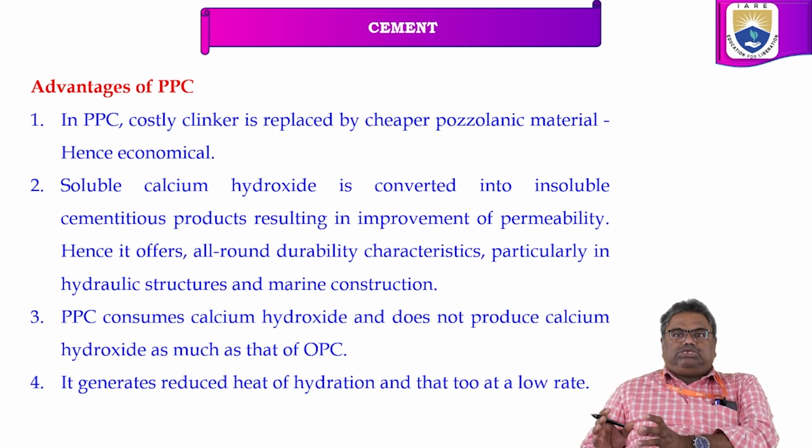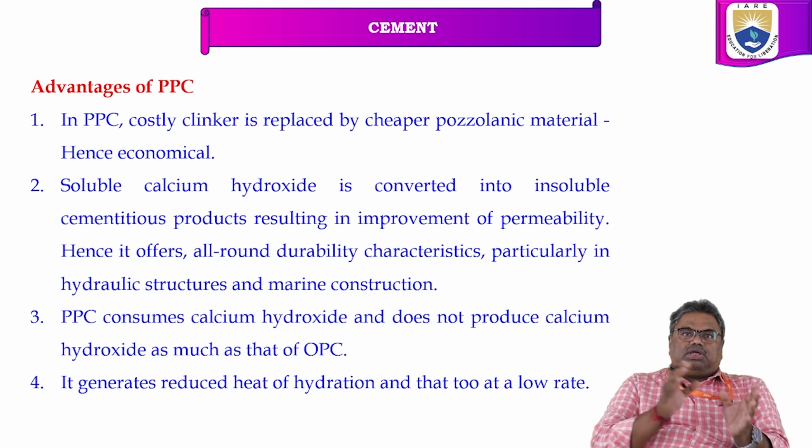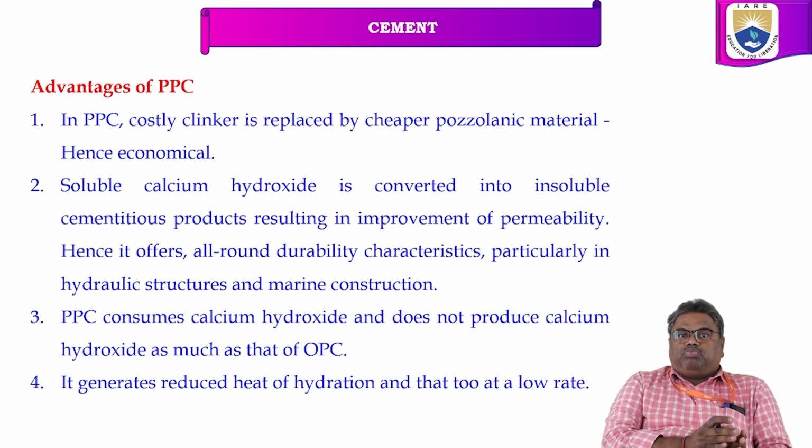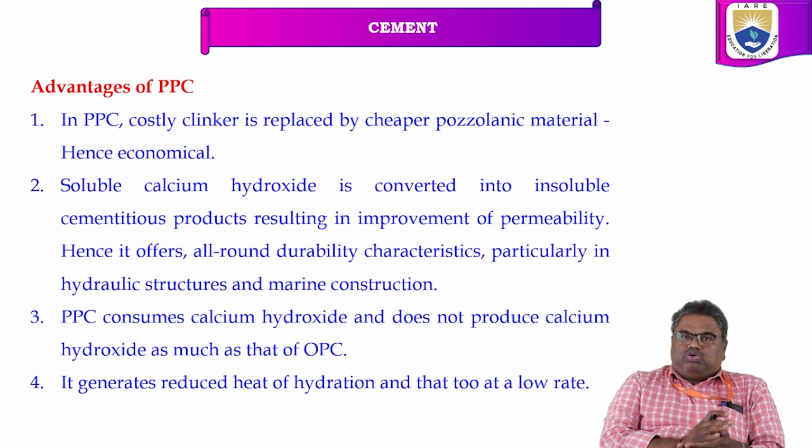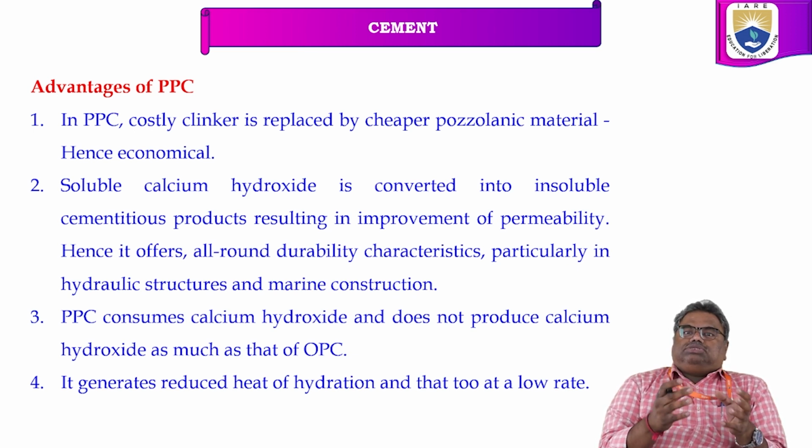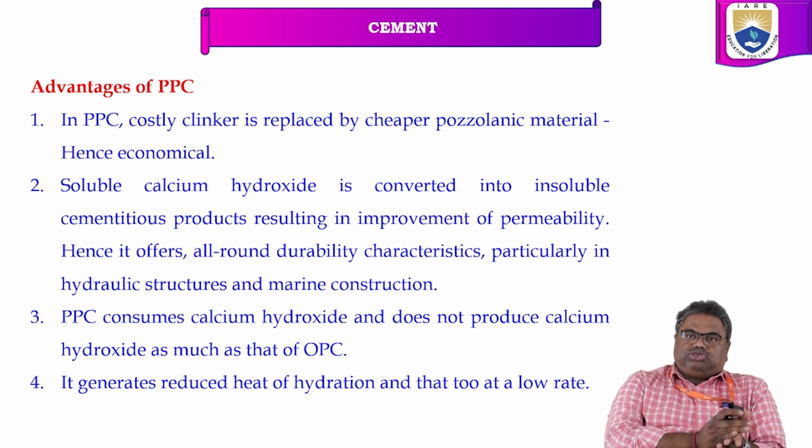That calcium hydroxide also reacts with the pozzolans, and it is going to form another CSH gel. CSH gel is directly connected to the strength.